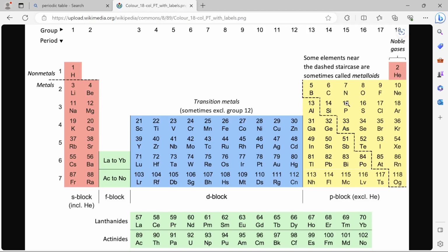So when you put an impurity from group 5, let's say arsenic, into silicon, 4 of arsenic's electrons bond with silicon, and one outermost electron of arsenic is left. That extra electron contributes to the conductivity of the material.